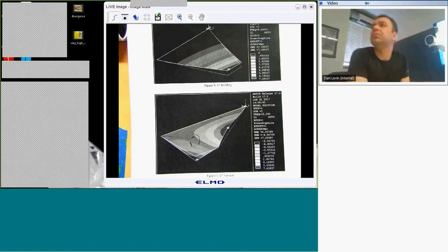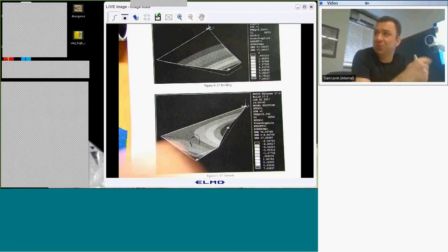Regarding the instrumentation, how likely is it that you reuse that wing after putting the strain gauges in there? Is it going to change whenever you try to take them out? That's a good question. Because you have them already stuck there, it's probably going to change some. If you want to use the wing in another experiment, you are welcome to do so. But if you want to detach the strain gauges and use them on a different structure, no.